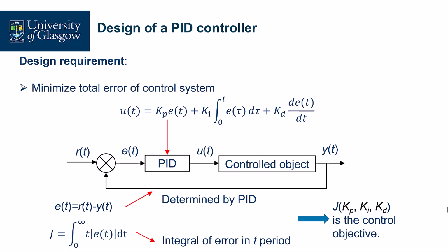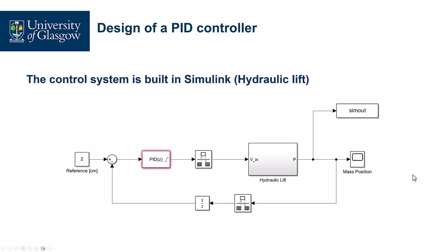So how do we build this PID control? We can use MATLAB's Simulink. Simulink is another MathWorks product, in parallel with MATLAB. When we build this control system in Simulink, this is the PID controller. Now based on this, we can write the optimization problem and the objective function.